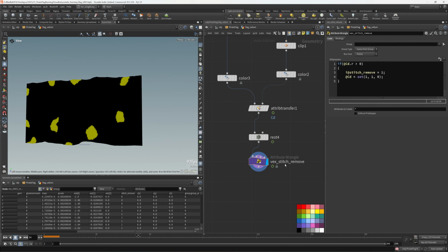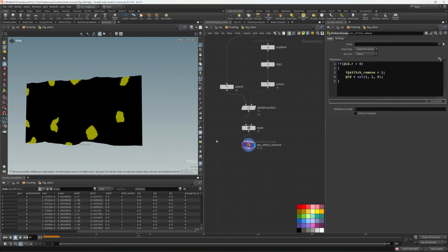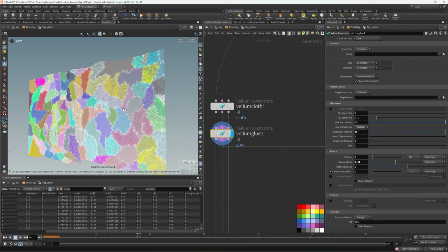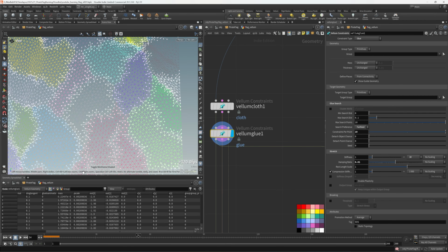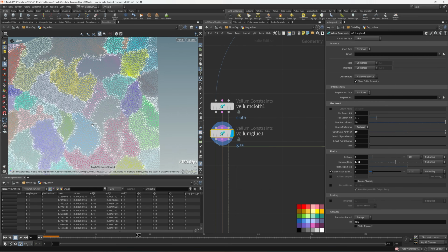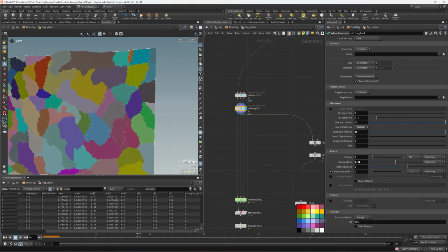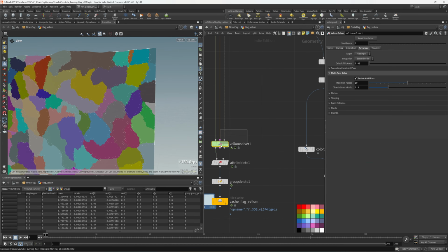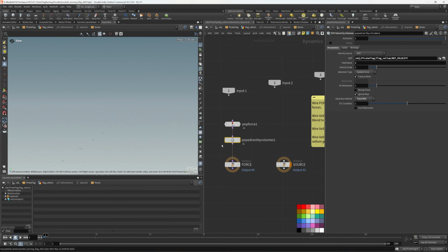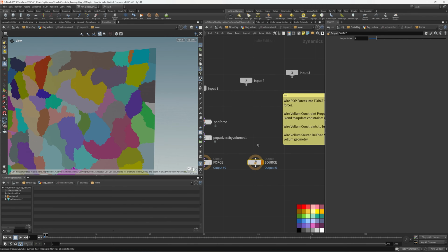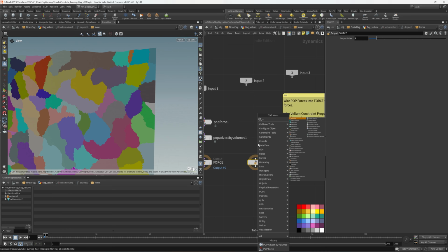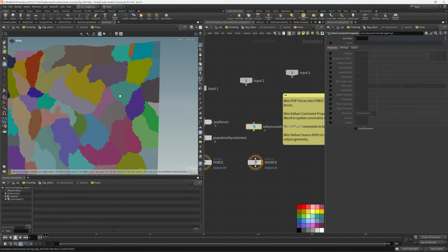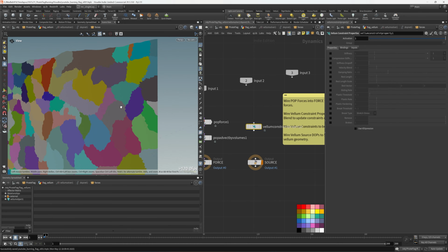What is this stitch remove attribute doing in the simulation? With this stitch remove attribute, we are going to delete the glue constraint from the simulation, from the Vellum simulation. To create that, we need to dive inside the solver. In the source, we need to create a Vellum constraint properties to change and break the constraint, the glue constraint from the flag.